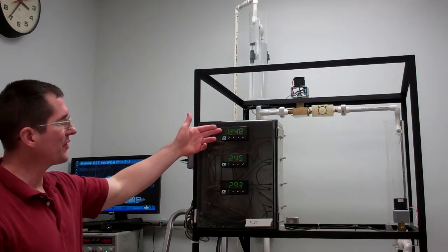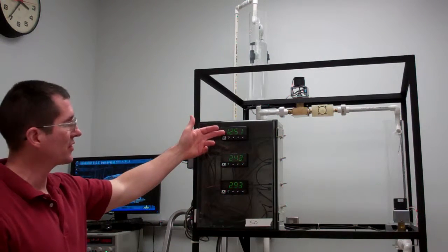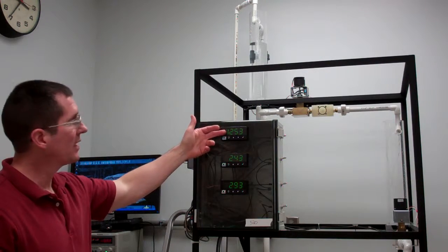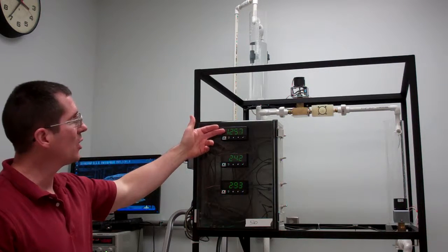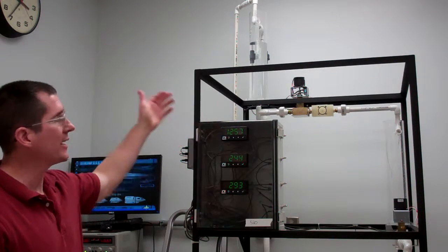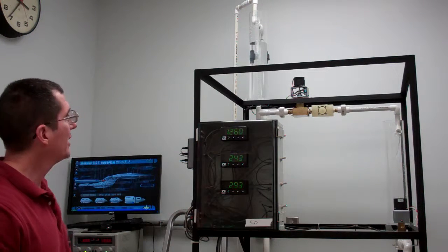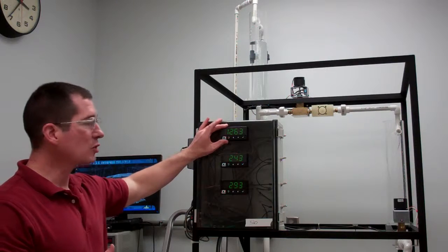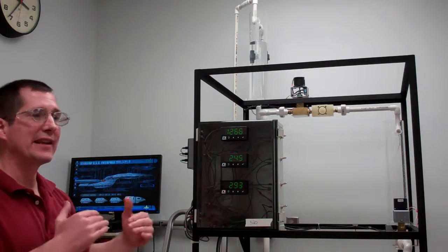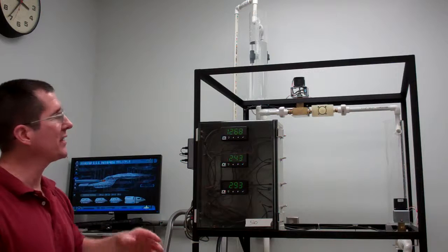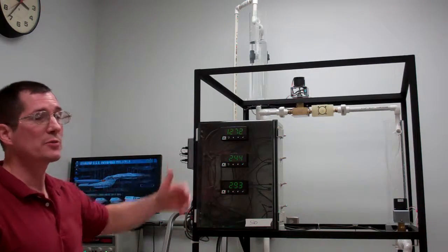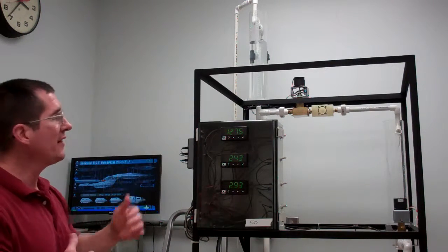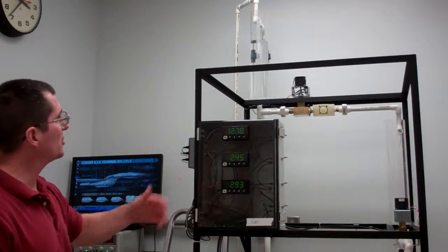What that means is with this measurement level rising, the inlet flow is higher than the outlet flow, and so we get an accumulation of water inside the tank. Now, this is all very important to understand because in order for the controller to make control decisions, it looks at the error, which is the difference between the set point value and the measured value. So it's not just increase or decrease, but the actual difference between the two. That's called the error, and that's what the controller makes decisions on.